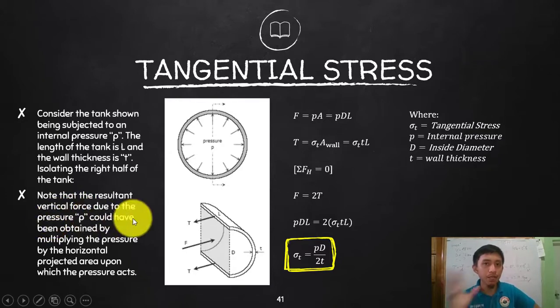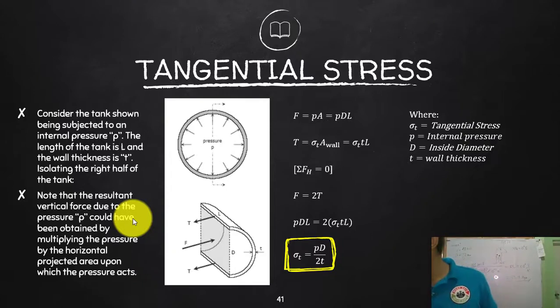If you say pressure, that is same as stress, because stress is actually a pressure. If you say pressure, that is intensity of load per area. You recall your physics? That is a pressure. Again, force is distributed within the area. We only call this one stress if we are now referring to the material itself.